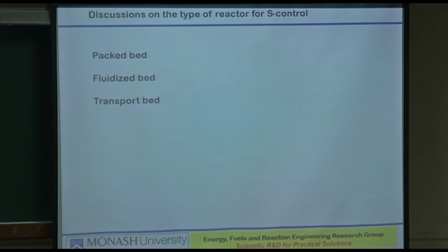Okay. So to answer your question, in any of these beds, the first thing that is seen is the instrumentation that is kept, the pressure drop instrumentation, and it is the pressure difference that tells you whether there is good contact or not. So if the pressure at the bottom of the bed and the top of the bed are exactly the same, not much contact is happening. The gas is coming and going out.